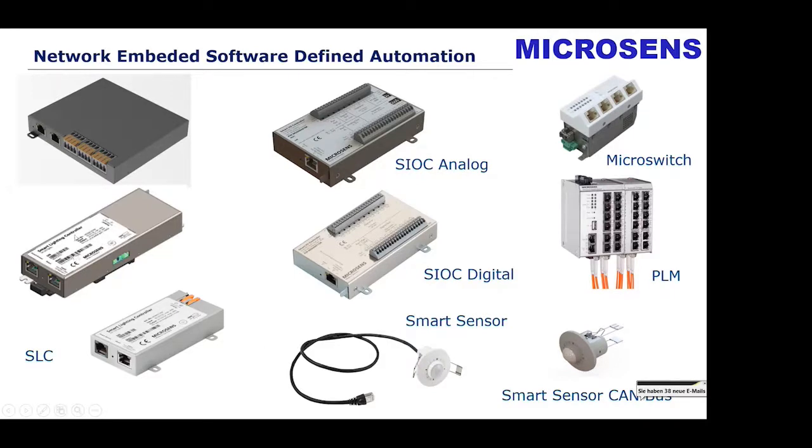In the middle, you see the 2-channel smart light controller, which is going up to 50 watts per device. In the same way, you have a PoE port, which provides the power supply and data, and you can connect up to 2 LEDs. And on the top, you see the 6-channel smart light controller, which is able to be connected to a 90 watt PoE port. And you can run 6 independent light channels, fed over PoE with data and power.